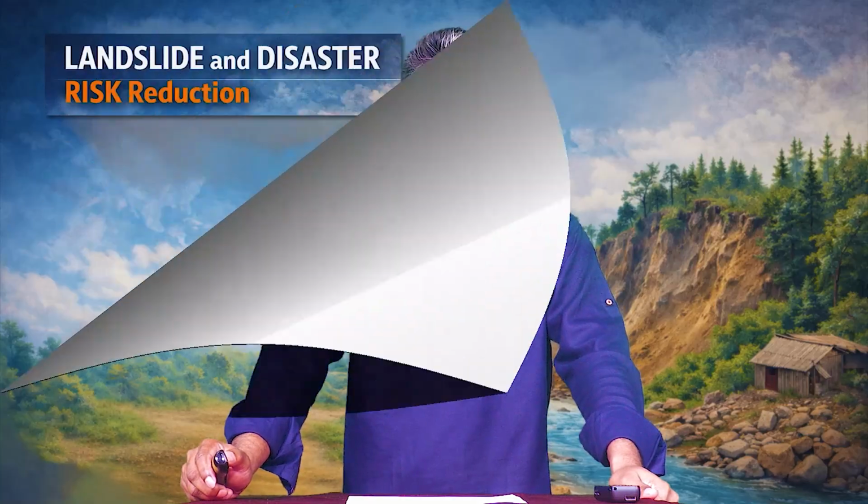Freeze-thaw cycles. In high altitude areas like the Himalayas, water seeps into cracks during the day, freezes at night, and expands. This repeated freezing and thawing acts like a natural wedge, splitting and fracturing rocks over time. The rocks become weaker and more likely to fall or slide during rain or earthquakes.